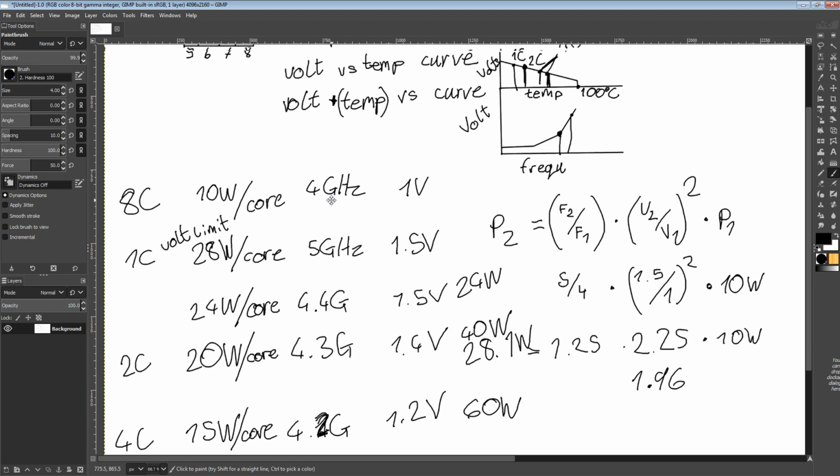I assume AMD's using a curve because the frequency changes very gradually depending on the workload. You can run 8-core workloads where, depending on the workload, it'll run a couple megahertz higher or a couple megahertz lower. Like Cinebench runs a higher frequency than Prime 95. Different settings of Prime 95 run at different frequencies. Almost any workload has its almost unique frequency voltage profile.